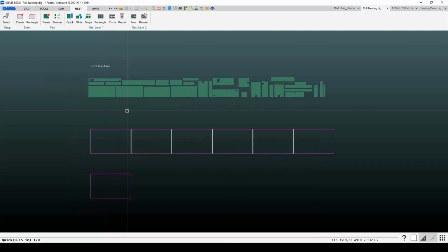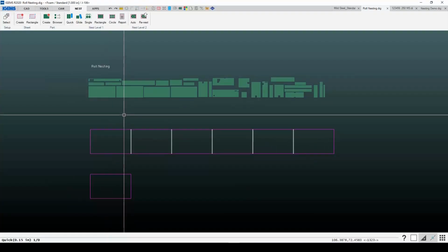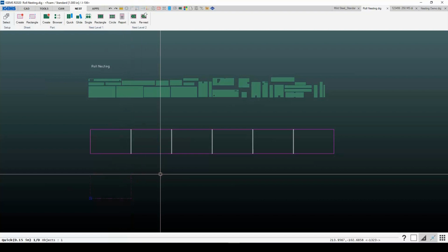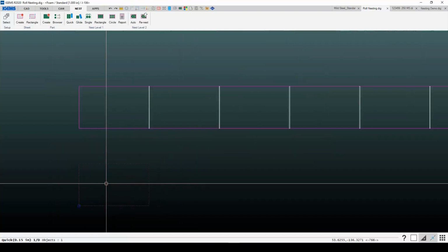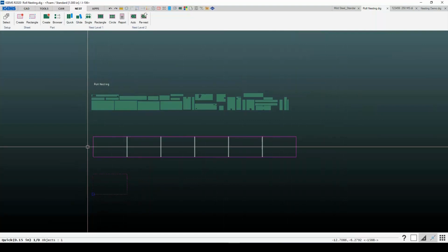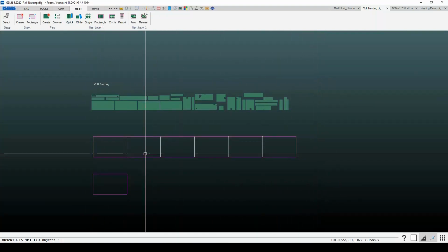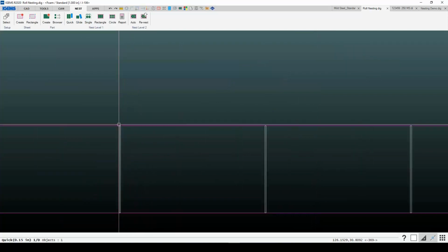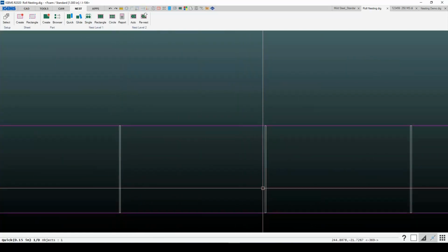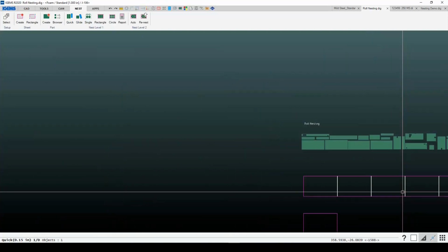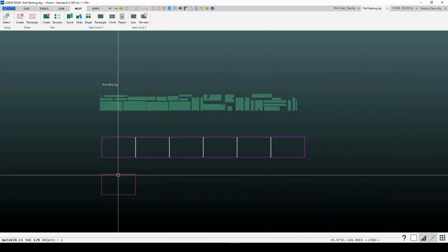All right. So a couple ways of doing that. You can either nest it onto individual rectangles of your cutting envelope, or you can nest onto something representing the entire length of your roll of material. And then you can basically set up obstacles here based on the extent of your cutting envelope where it's not going to nest things into.